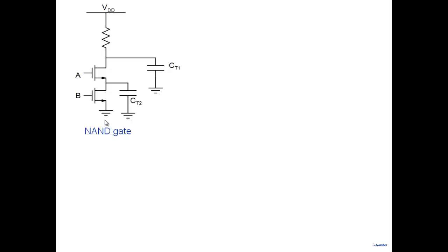I'm talking about dynamic power in this particular gate here. This gate charges and discharges this capacitance. Two capacitances are associated with this particular gate. Now note, you may be thinking, well, there's an input capacitance here and an input capacitance here. But that part will be discharged by the previous gate. That will not be the dynamic power dissipated in this particular gate. This particular gate dissipates power only because of these two capacitors.